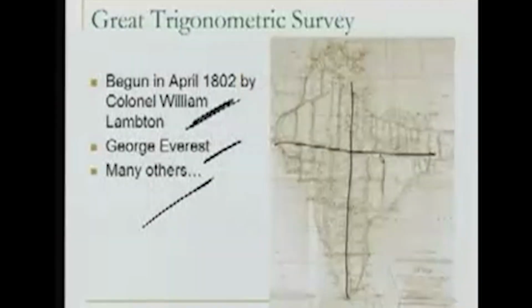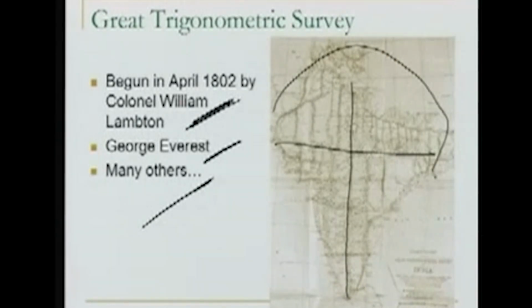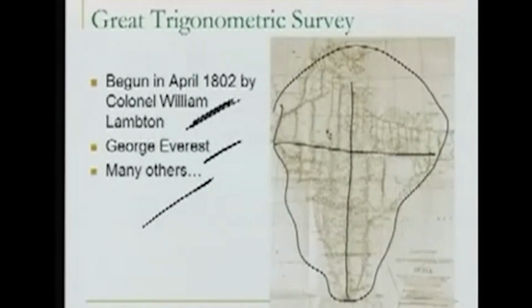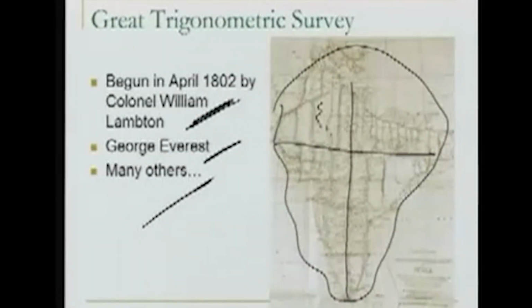And ultimately, at the end of the day, we have a network of triangles, as we have already discussed. This is the great iron pattern all over India, in which for each point we have the coordinates known. So we can make use of these coordinates now in order to do the survey in other areas and relate our survey to the rest of the survey of the country.